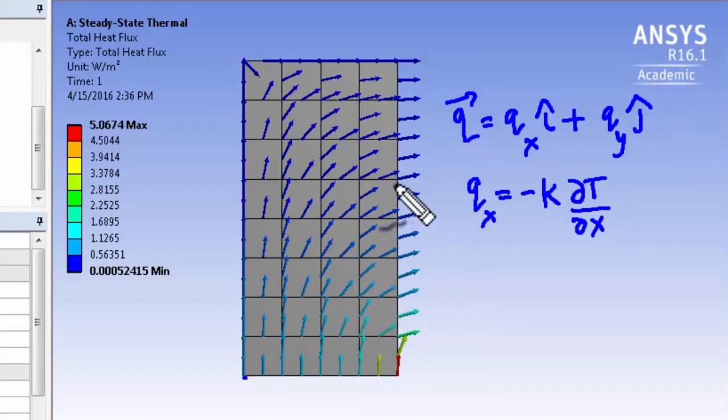And then you can see that heat is flowing out to the fluid over here. And you can see that though the heat flux is supposed to be 0 at these boundaries, it's actually a very small value. So as we saw, the natural boundary condition is satisfied only approximately, whereas the essential boundary condition is satisfied exactly. And we see the effect of that there.